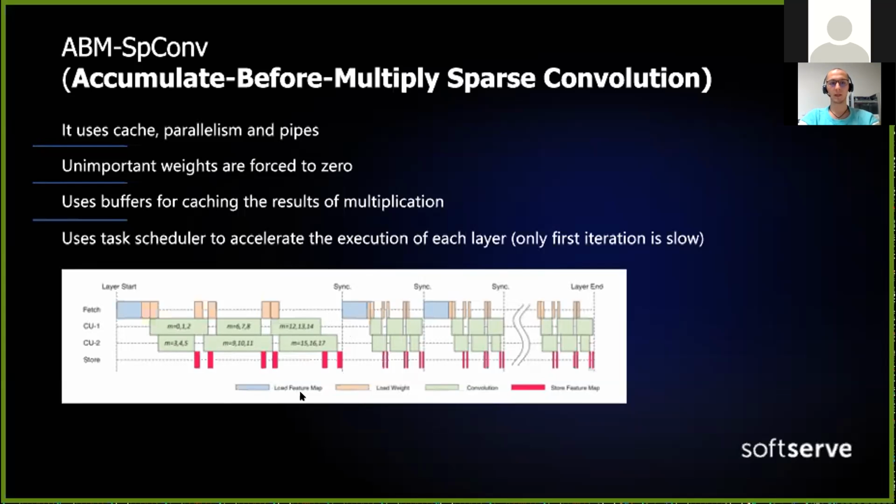And the best thing in this approach is that they use from 38 to 50% of DSP blocks, and the same for on-chip memory, because all articles about neural network acceleration and all experiments in the articles use from 98 to 100% of DSP blocks and memory, so it makes it impossible to have something else on the chip, but only the parts that use convolution.